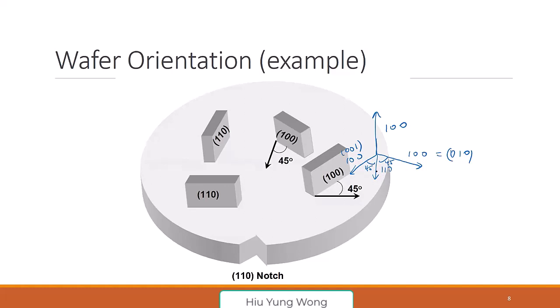Okay, but now we're talking about FinFET, right? Then you grow the FinFET, you see that this is 100, the face, this is the face, right? And exactly, you see I put 100 in this direction, it is 100. Okay, and then you can rotate it to perpendicular to this one, then you get 110, right? So when you design the FinFET, it's more complicated because now you have 3D and you can rotate them, right? But you don't want to rotate them arbitrarily because this increases your layout area. You are going to have a lot of irregularity.